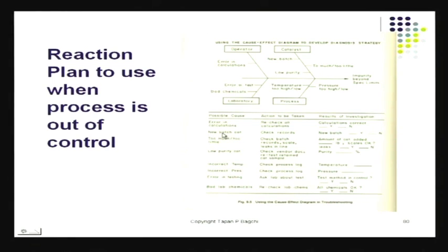I've listed that, and I do the calculations there, redo the calculation, and I turn to the process and make sure that I've done all the rechecking and so on, and I mark right here, have I found the problem? Calculations correct? Yes. That means I need not really worry about this factor, then go down to the next one. New batch of catalyst added, is that true or false? That could have caused the problem. This is also not a problem. That means no, it's not a new batch.